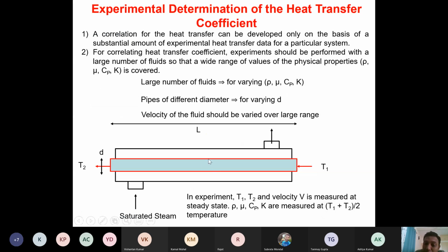So in the case of the Peclet number, how fast the heat transfer takes place across this entire pipe is looked at based on conduction. Remember, there are two factors when heat is being transferred to the pipe. When we look at convection, it also counts the conduction, isn't it?